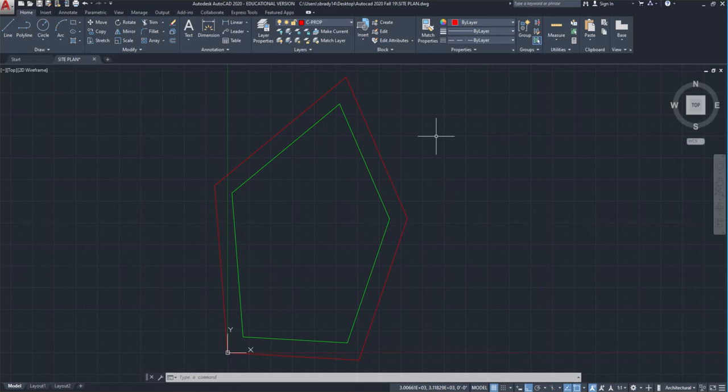Because AutoCAD recognizes that we have extremely large objects and extremely small objects, and that we will be using the same line types for those. But in a small object, the line types will look great, right? There will be an adequate amount of space between the dashes to make it look dashed. In larger objects, there might not be as much space to show those line types appropriately. Okay, so essentially we have LT scale we need to worry about as well.